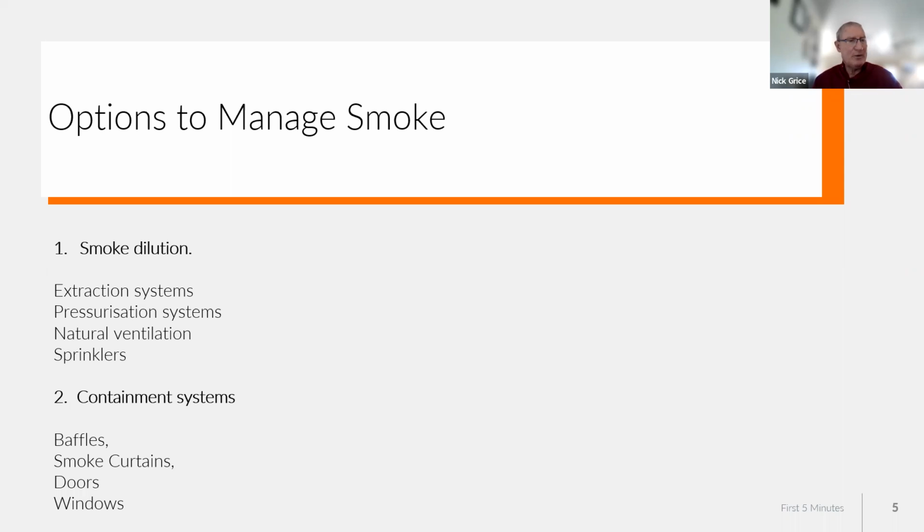And if you think about it, what we've been on about so far with smoke detectors, thermal detectors, barriers, compartmentation, fire doors, firewalls, all that type of thing, all these passive and active systems work together. So if you've got a detector go off, it can close the door, which causes a compartment. It can start smoke extraction systems or pressurization systems up at the same time. It can start up building management systems. It calls the fire service. Just one detector going off does a whole array of things, which we will explain later on in other sessions when we go into fire indicator panels and things.